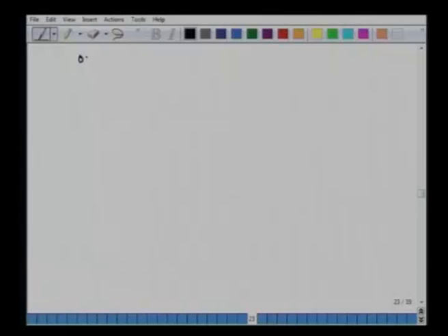In this system, what happens when there is no reboiler? We will have to make certain modifications in both the McCabe-Thiele method as well as the Ponchon-Savarit method. The idea is how we can address this starting from first principles, or by making some analogy with both methods, Ponchon-Savarit and McCabe-Thiele. Okay, so let's see what we do here. Let's write down the operating line equation.